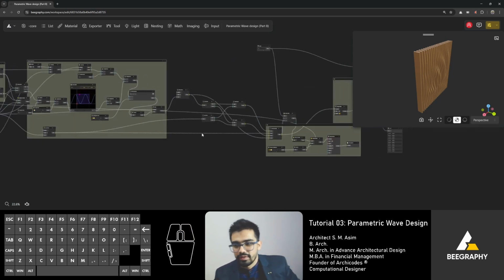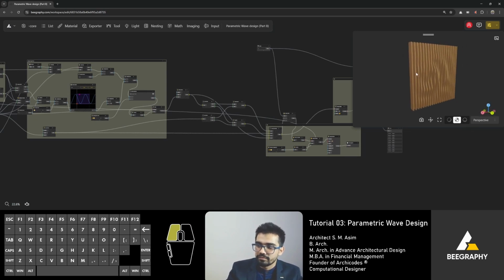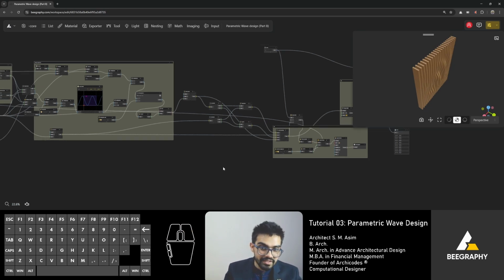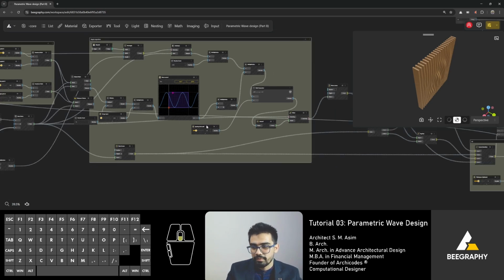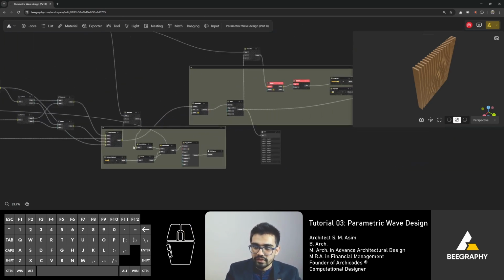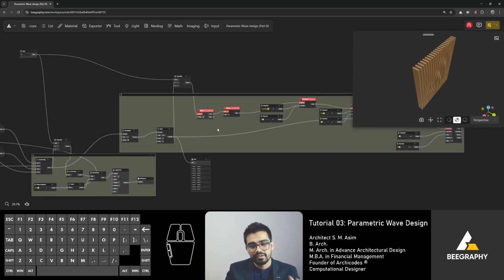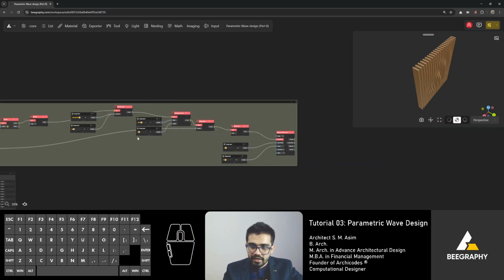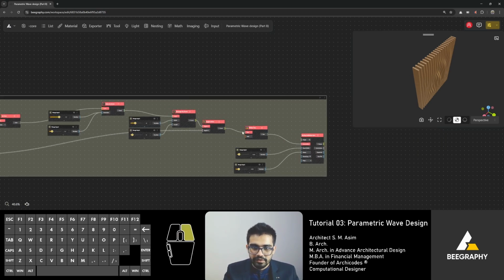All right, so I hope you found this useful. You followed along. Keep in mind the dampening concept that you can use for your own scripts. The multiple attractor logic, instead of distance, we used closest point. So remember that. For 2D, you saw what we did. We extracted the curves, we did change origin to put all of them at one point, oriented it in XY plane, and used nesting guillotine.